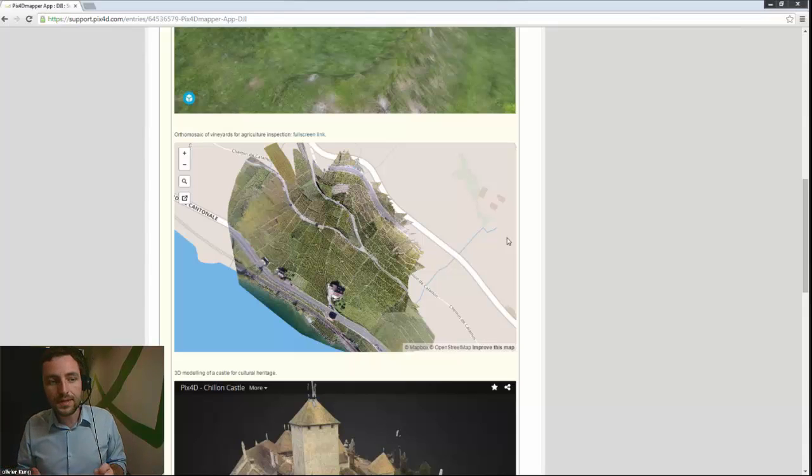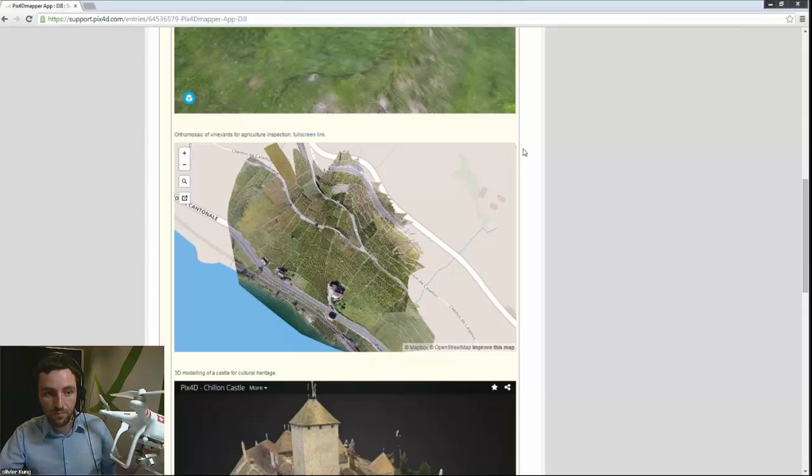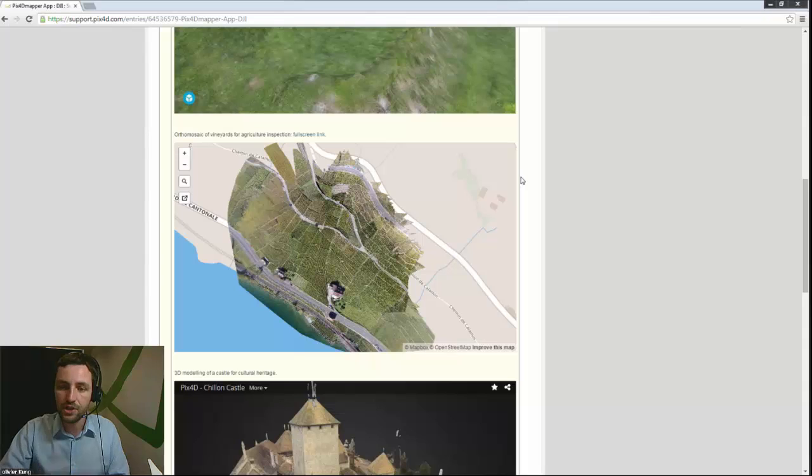So if you just have a GoPro and you take images, it's going to work, but it's going to be harder to do quality control and to have a very nice consistent overlap between each image. So right now we really recommend, as an easier solution, where you are more certain that it will work every single time, to use the DJI Vision Plus with the integrated camera rather than to try to have a GoPro on top of a drone. Unless you have a specialized drone which is able to also geotag each image correctly.